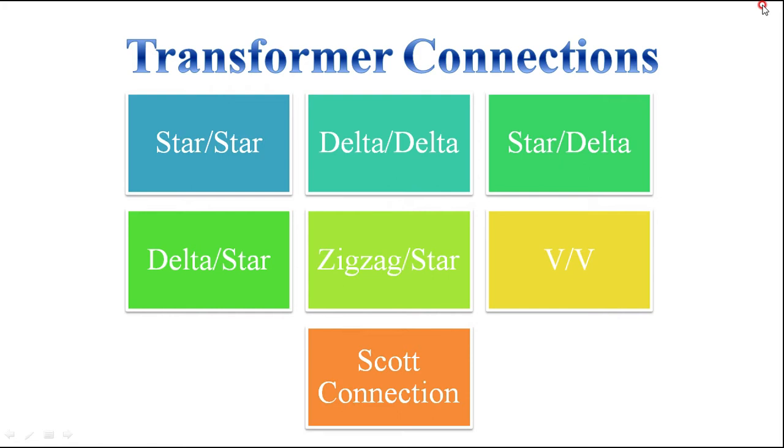Means we have a single unit of a three-phase transformer that can be used, but we know that there are certain disadvantages of a three-phase transformer because its construction is very huge and the weight is very high, and because of that there is a problem of transporting and installation. However, compared to a single unit of a three-phase transformer, we are going for three single-phase transformers for three-phase transformer connections, because another advantage is that if any fault occurs on